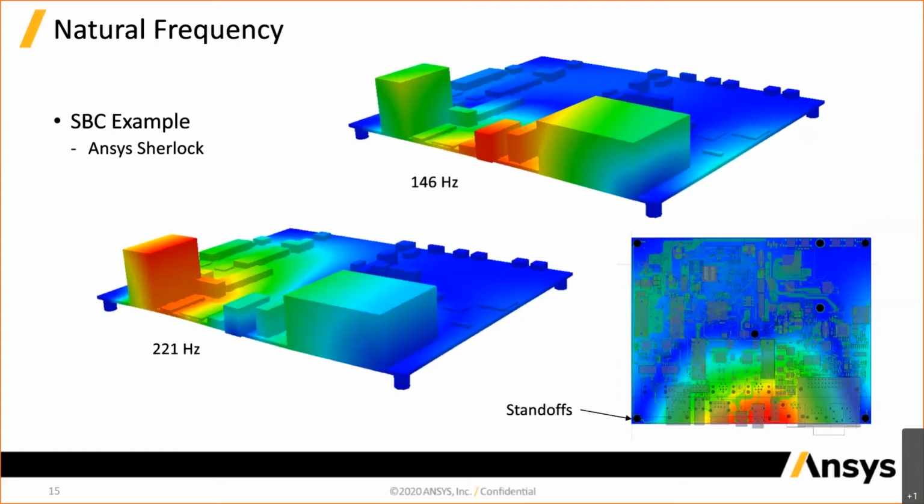It's got some really large connectors on the one side. There's unsupported span right there. You could potentially see issues at around 146 hertz. Only if those are through-hole parts, so chances are them having issues is rare. But if you were to stick a QFN or something like that in that area, you could see issues with it.